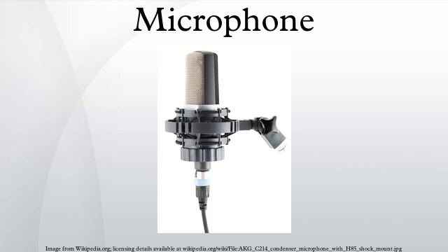However, there is at least one other practical application of this principle, using a medium-size woofer placed closely in front of a kick in a drum set to act as a microphone. The use of relatively large speakers to transduce low-frequency sound sources, especially in music production, is becoming fairly common. A product example of this type of device is the Yamaha Sub Kick, a 6.5-inch woofer shock mounted into a 10-inch drum shell used in front of kick drums. Since a relatively massive membrane is unable to transduce high frequencies, placing a speaker in front of a kick drum is often ideal for reducing cymbal and snare bleed into the kick drum sound.